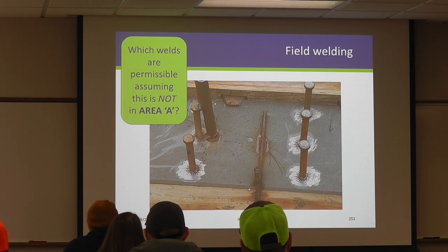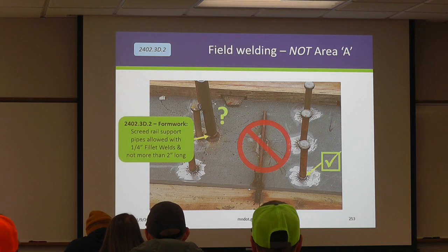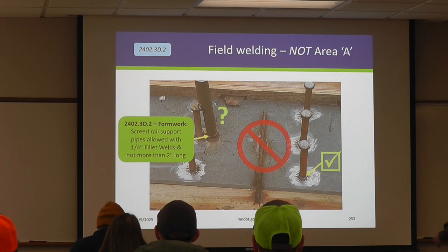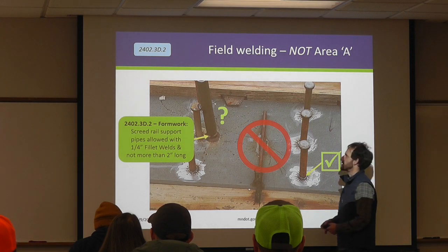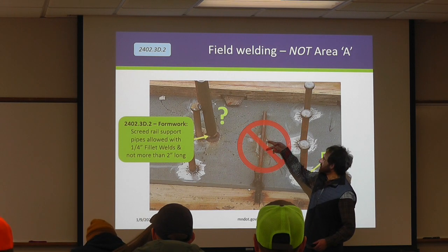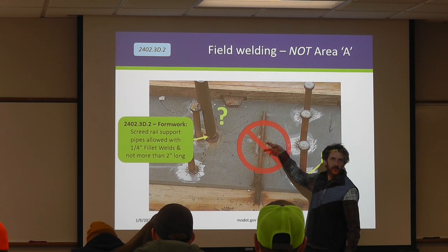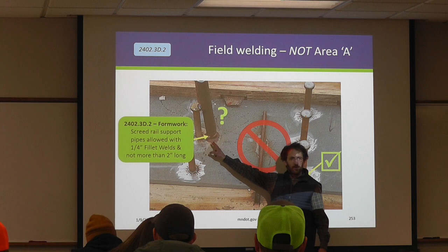Do we want these bolts here? No, we really don't. The spec book does allow for a 1/4 inch fillet weld that's not longer than 2 inches. So that's in this formwork section of the spec book. Visually, this looks like it's more than 2 inches. So we want to allow here. In theory, this one might be okay.